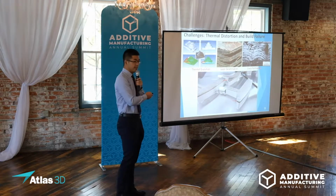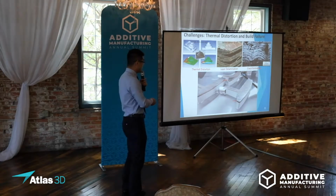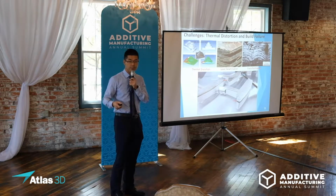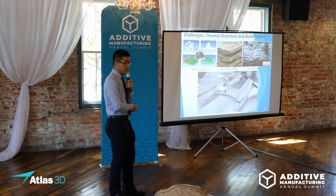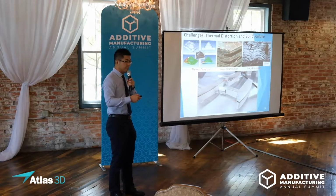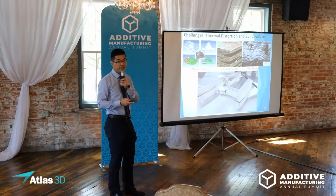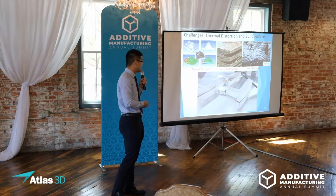This is a story that happened at iCanco. When we tried to print this part, we chose this horizontal build orientation in the very beginning and tried to use this strong support to hold it down to the build platform. And finally, we got this problem. You see that at this corner, you got some delamination, and after this delamination, the distortion will be very large, and the recoater blade tries to collide with the part, and finally, we got a failed build. So this problem is very common in the 3D printing process.